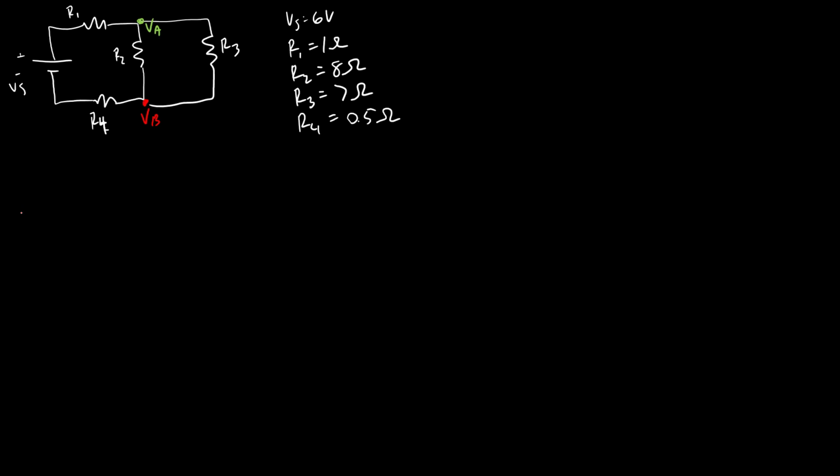So we flipped over to a clean slide here, and we are going to go through that exact same process for node B, where we have currents that we defined previously, I2, I3, and then we're going to have I4 exiting that node. I forgot to redraw my signs and all the resistors. Again, you got to be careful to keep track of your sign conventions. Plus, minus, plus, minus, plus, minus. Okay, so we are going to apply Kirchhoff's current law at that node, where we have I2 and I3 coming into the node, so they're going to be positive, and then minus I4, since that is leaving, that's going to be negative, equals 0.